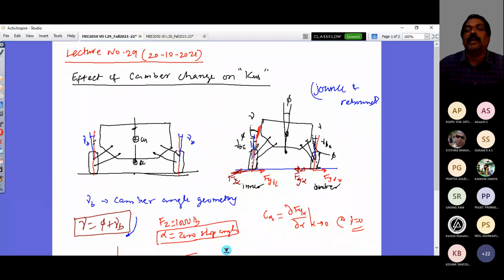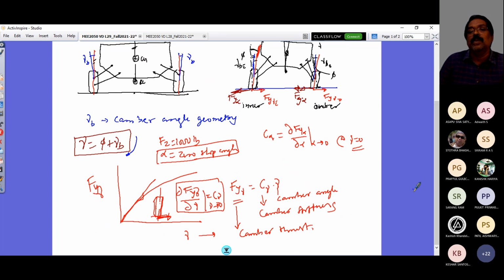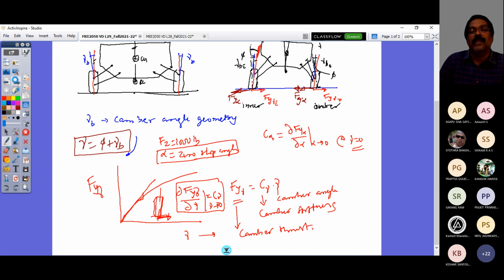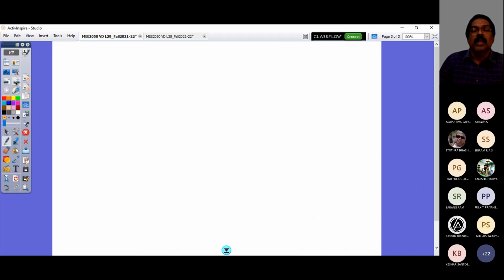So I do not bring in here my roll and roll rate and the moment taking here and putting normal load and so on. You may wonder where is that weight. Those terms I'm not drawing. If I put the same in this diagram, or the diagram I used in the previous case, along with that if I account for camber, I will have all these three terms coming. For convenience, we are looking at an individual effect, and that makes us understand these derivations easily, right? Now let's look at one more effect, something called the roll steer effect.